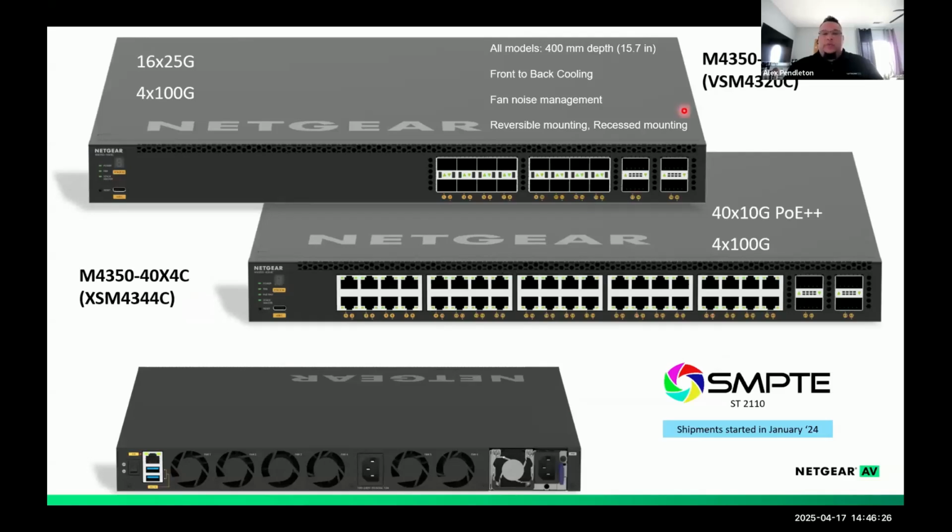Two of our switches, as we mentioned earlier, have the capability of being a grandmaster or boundary. The big difference is the grandmaster is the main sync clock for the network. A boundary has a sync to follower clocks and ordinary clocks, but also has a reference clock somewhere else in the network.